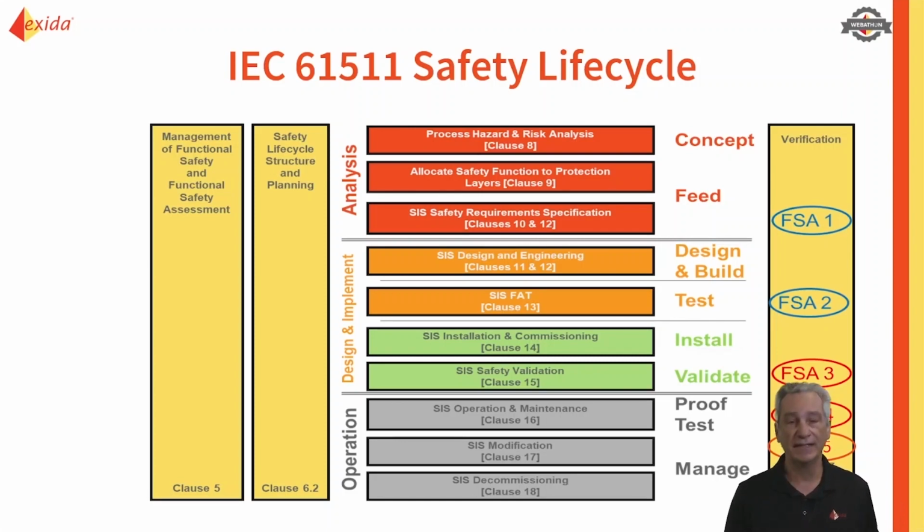We can do the risk analysis, we can define what our safety instrumented system needs in terms of safety instrumented functions and the target SIL levels that they have to achieve to reduce and mitigate the risk. And we can do all of that correctly and design it, implement it, we're great. But if we don't do the operation and maintenance side properly, then very quickly our performance will degrade.